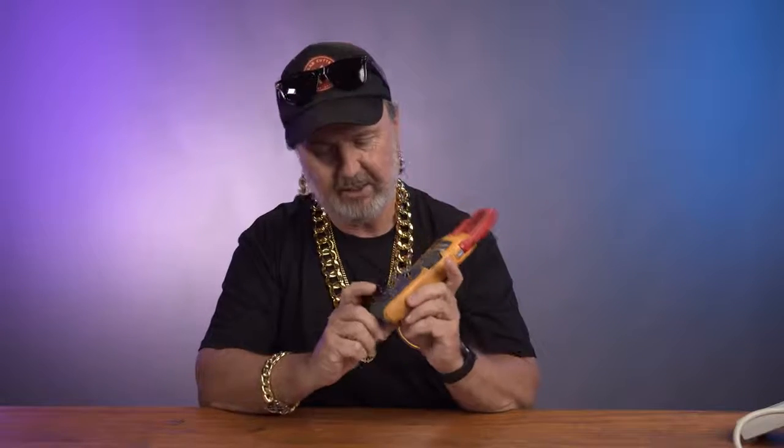So therefore it is really an electrician's tool because you're going to be in a switchboard. You can't just clamp this around a power cord, which embarrassingly I had tried once and wondered why it always measured 0. It's got to measure one directional flow, so it can only go around one conductor, like the active conductor. This particular model has a button down the bottom here, which says inrush.